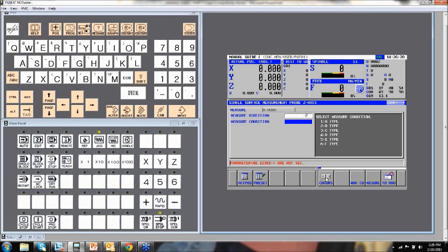And of course, it comes up and tells me that I don't have the parameter set, and that's correct because in NC Guide I can't do that. And then I go in and tell it what my work coordinate is, and when it touches the top of the part, what I want that value to be. The way I program, I'd always make that 0 or some minimal plus amount, but that's what it wants there.